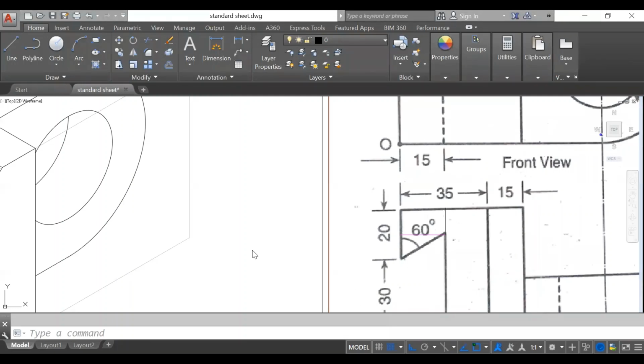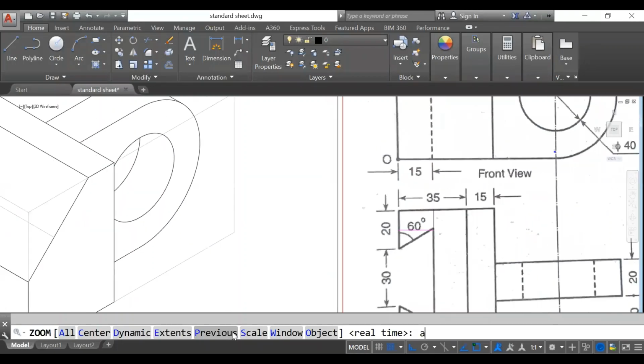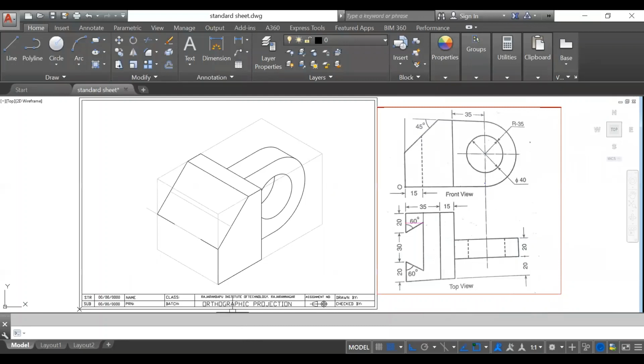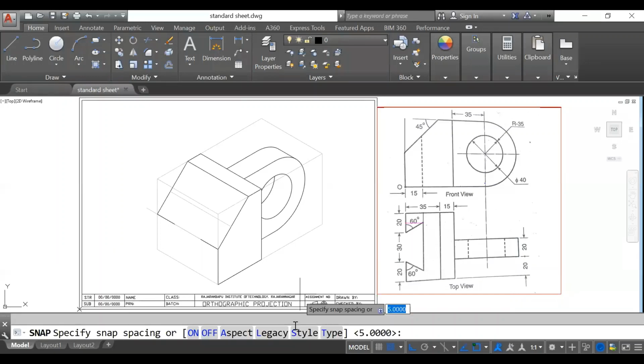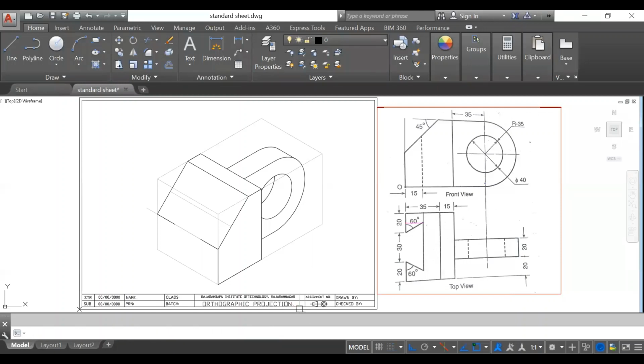So already I have told you the angles will not work in an isometric. So you have to always consider that dimensions or distances. So 11.34. So from this to this, 11.34. From this to this 11.34. So again, I have to go to the snap mode again. Snap. Here style, then isometric, 5, enter. Then this I have to off.